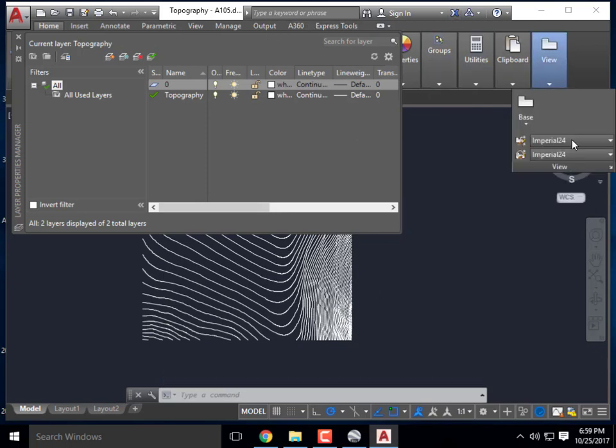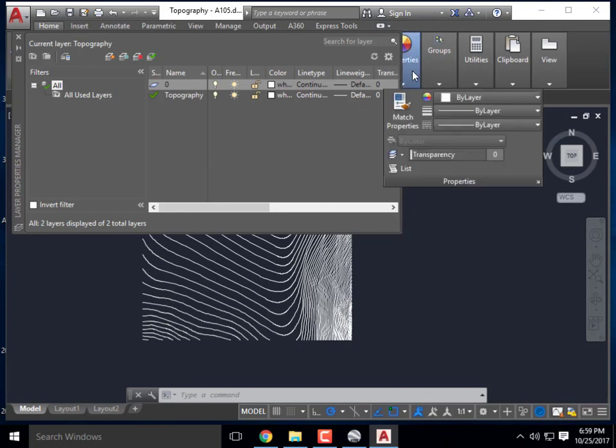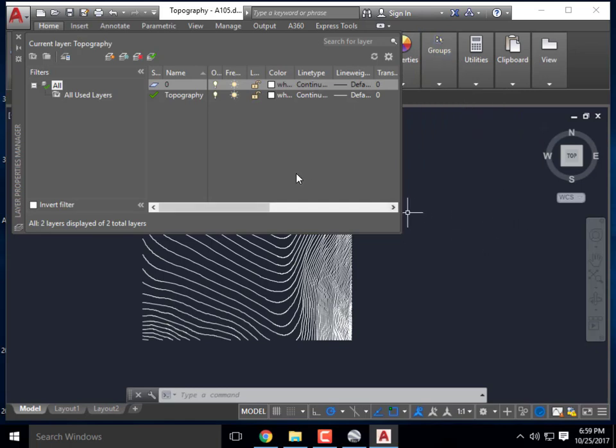My computer screen at work looks a little bit different because most people that use AutoCAD customize the user interface as they prefer to work on it, because they know they'll be working on it for long extended periods of time. So pardon me if I can't find things every once in a while. It's just because my AutoCAD's different in my office. But if you type in layer, you'll get the actual layer toolbox that pops up. In my opinion, it's much easier to work with than the little drop-down menu. But the drop-down menu works well if you're just looking to do a quick change.